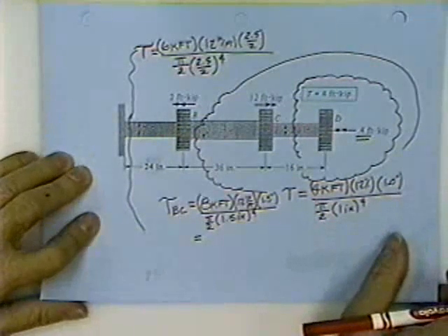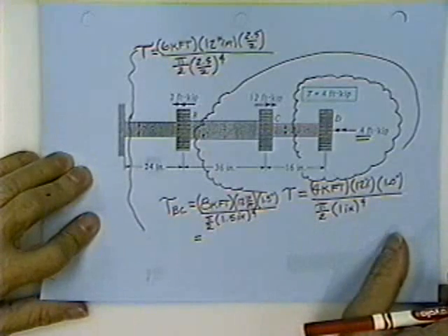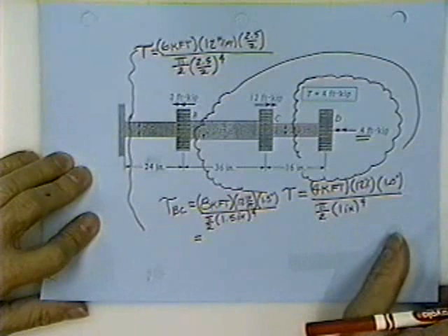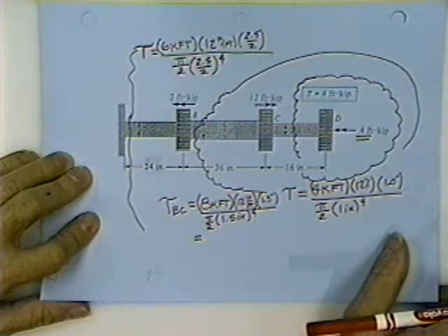I could also solve for the diameter were the guy to give me the torque and give me the allowed stress, then I could turn that around and solve for the diameter necessary. I'd simply pull out all of the D terms or all of the radius terms on the one side of the equation and stick all the other terms over on the right hand side.